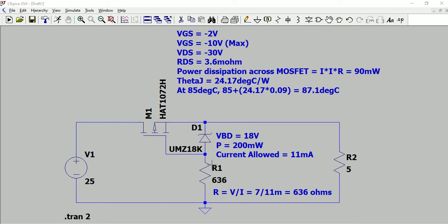So why resistor only here is, once this Zener starts conducting and this potential starts increasing, the entire current will flow through this resistor only, because we know the MOSFET has a very high impedance. So we have to limit the Zener diode current to ground only. Okay, so that is why this resistor is very critical.